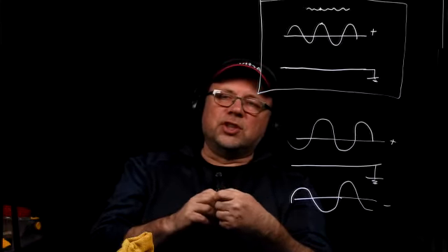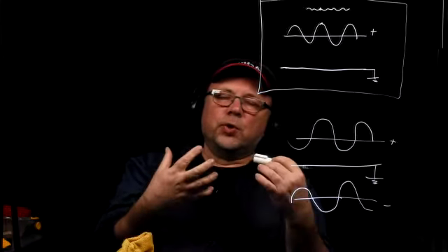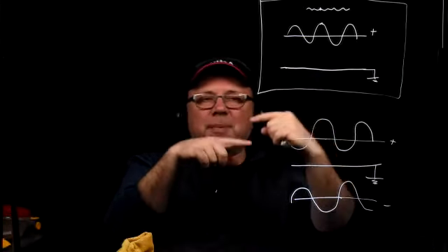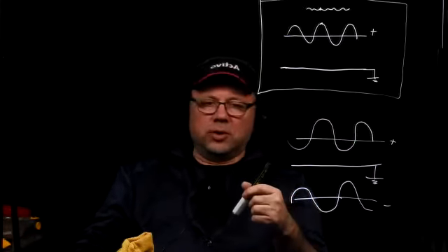What a differential amplifier does is it passes the signal through if it has two signals and they are 180 degrees out of phase, so they're opposite. One goes up, the other goes down, and they are mirror images of each other. Then it acknowledges the signal as a signal and passes it through. Anything that is in phase is going to be ignored by the differential amplifier.